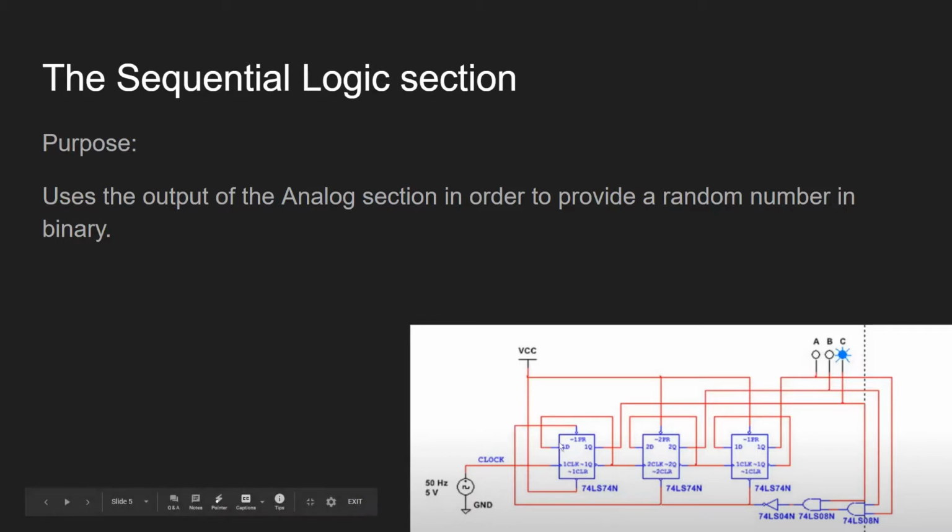And basically, we only want to go up to 6. We can't go up to 7. So basically what you're going to want to do is, you see here it goes 1 1 1. These are 2 AND gates, so 1 1 1 outputs a true, and since these are active low, we invert it to be 0, and the preset and the clear work under that 0.